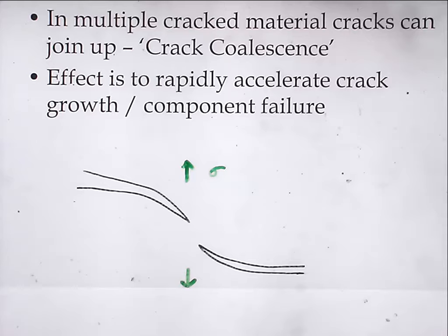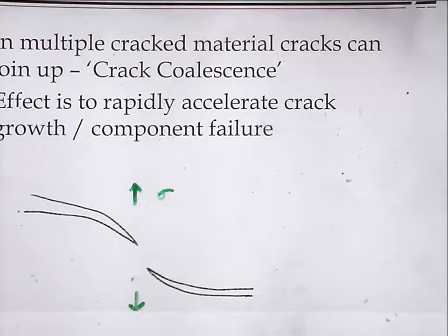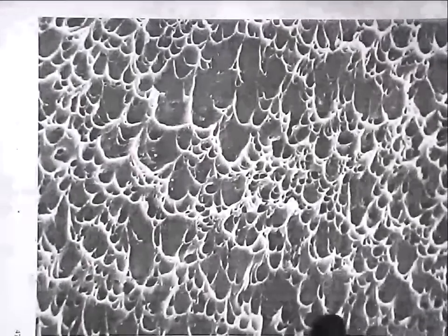That's a transgranular failure. Quite different in that what you've got is flat shear planes through the material. So you can't see individual grains. What you've got is a series of big flat sections, sometimes at slightly different angles to each other, but not this business of it going round the grains. So it is quite different because you've got these flat facets to the fracture failure.